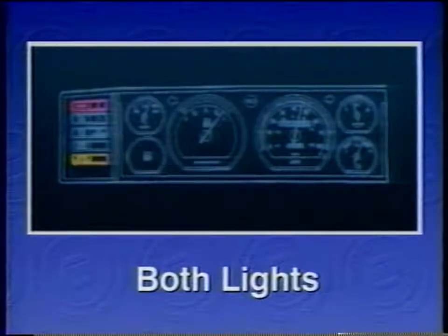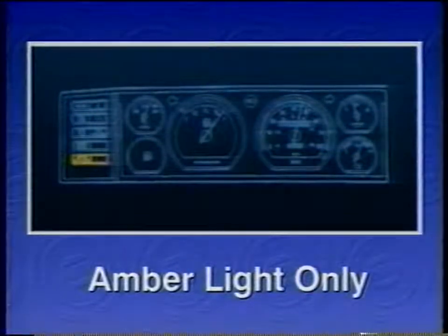When both lights come on at the same time, the problem is probably hydraulic in nature. If the amber light only comes on and the brakes operate normally, the problem is generally electronic or electrical.